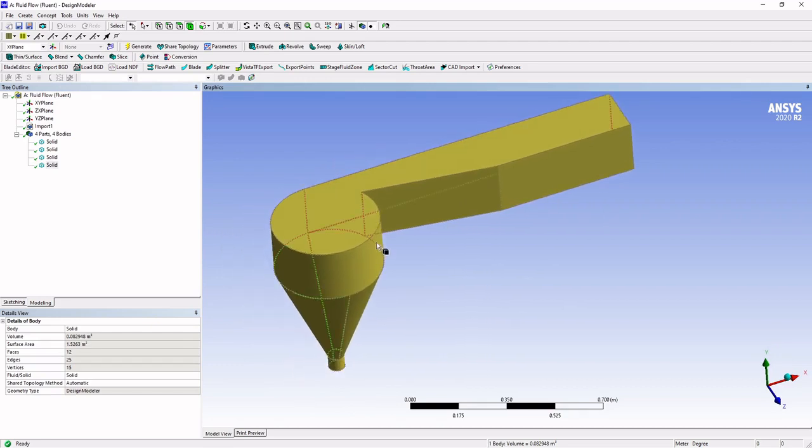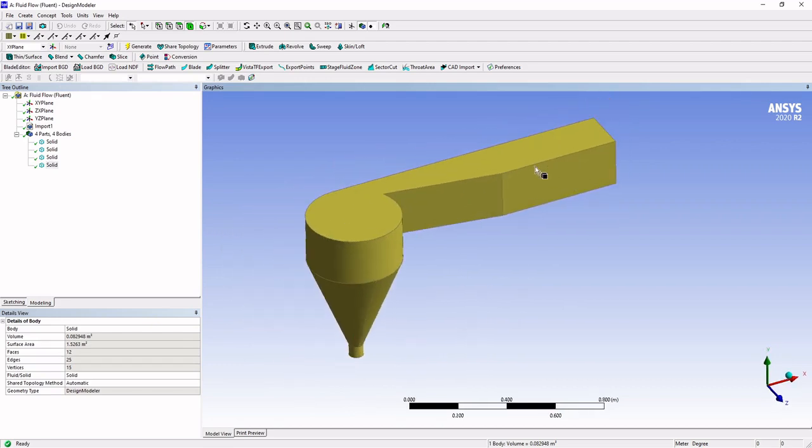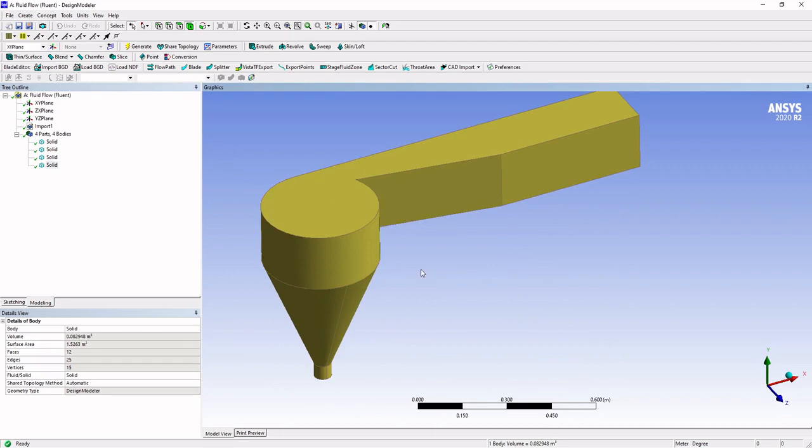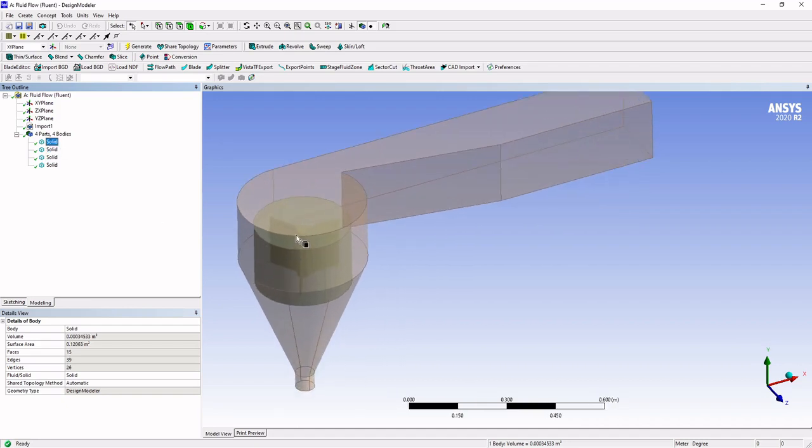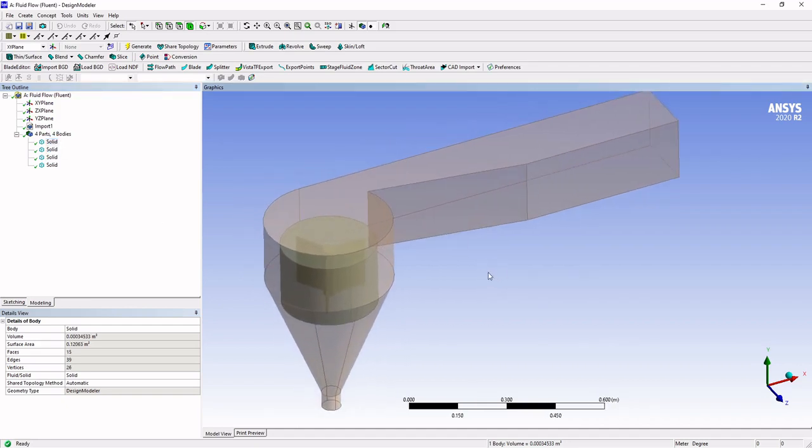So we got this solid body of your entire geometries. We got cylinder 1, we got a second cylinder, we also got the water turbine. What we actually need is only 2 bodies, one for the domain itself and another for the rotating domain.